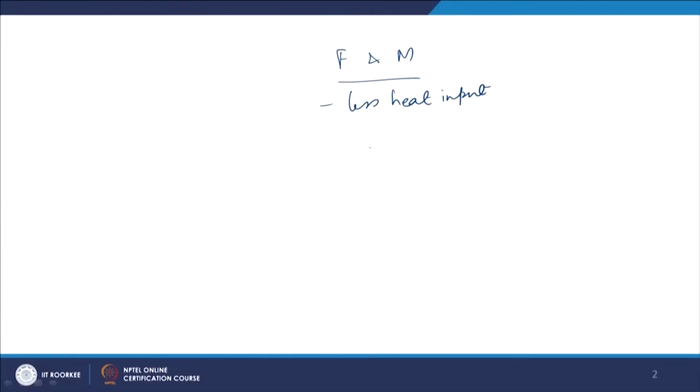So, that way, the electrical resistance is also more than that of carbon steel. Basically, because of these effects, in the case of ferritic and martensitic stainless steels, less heat input is required, because they have the same characteristic as that of austenitic stainless steel. Then preheating and post weld heat treatment are very much desirable. So, post heating is desirable.